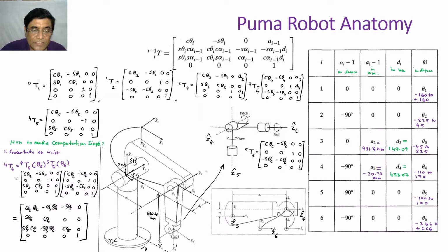This is also attached here, called the second coordinate frame. And as you know, the twist or the motion is about the Z1 axis, a vertical motion. So after getting the robot, wherever you find motion, you put your Z axis. That's the rule you have already studied.